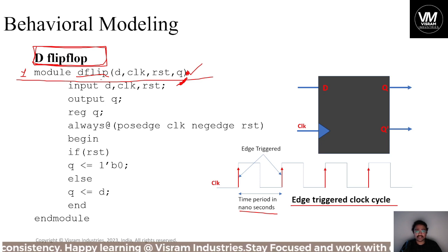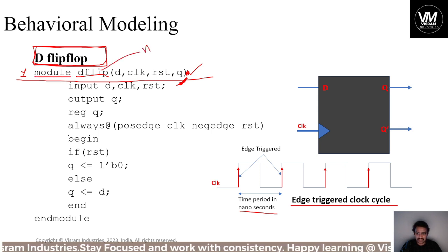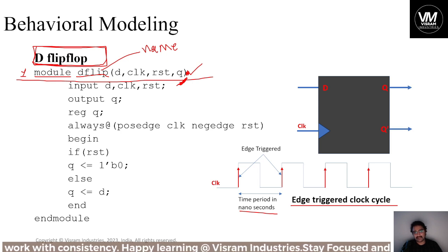Whenever you understand something to develop, there is a blueprint for that part or for that line of Verilog HDL code. For example, the blueprint here is you need to start with module, name it, name your device. Module is nothing but device, element, circuit, or whatever you call it, the entire design. So that design will be called a module. Here my design is the D flip-flop.